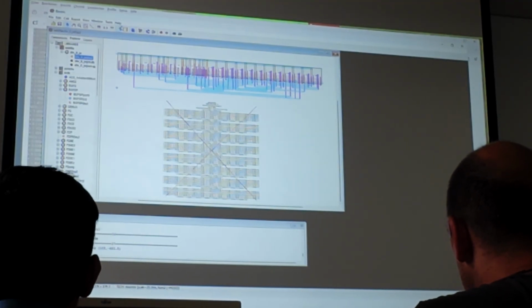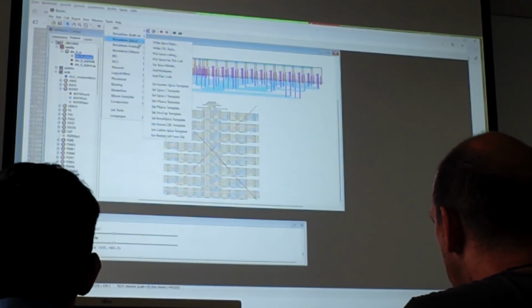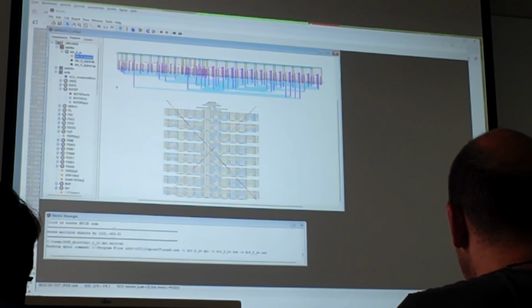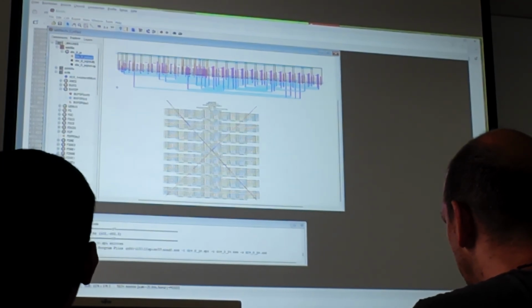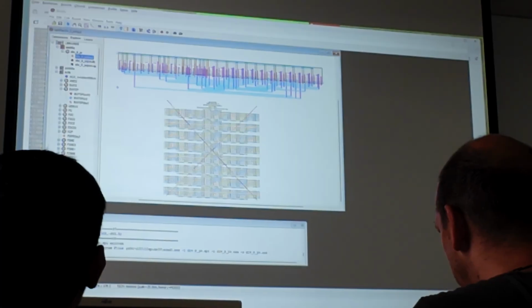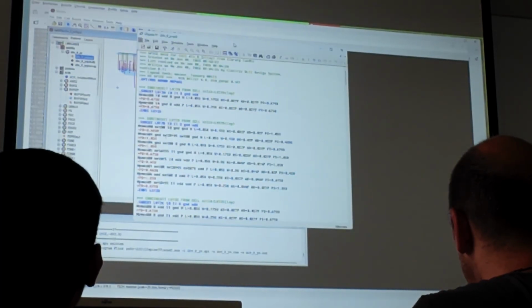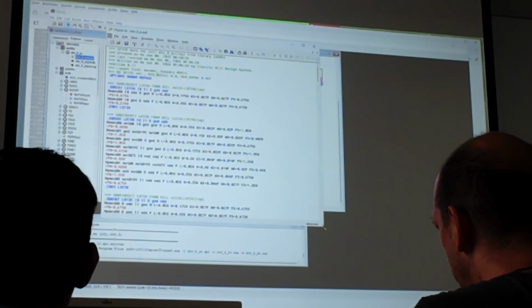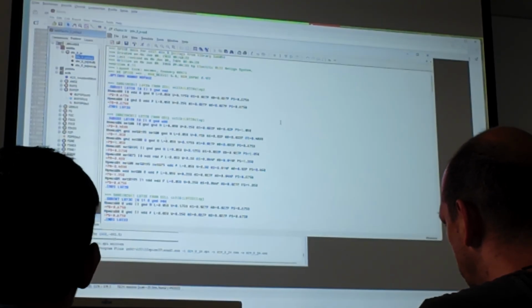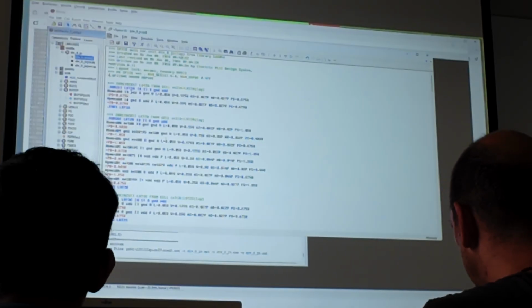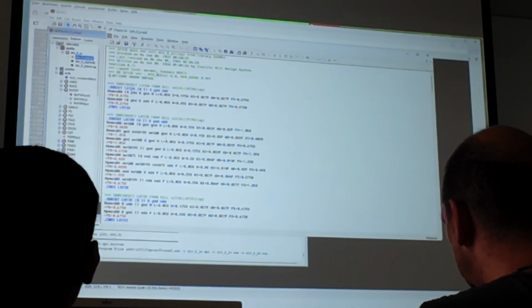Good, now we're ready, so we can start our LTSpice, right? So you have here your Spice stack. We get the error message about this options no name no page. We just comment it out. And then we see all the things we are expecting.